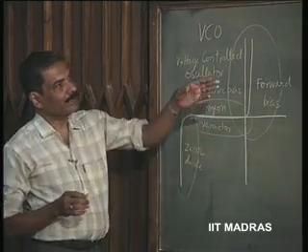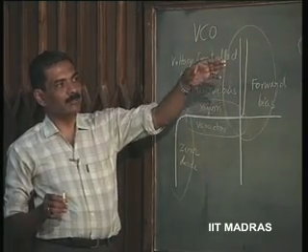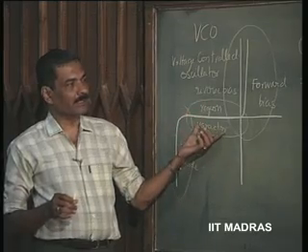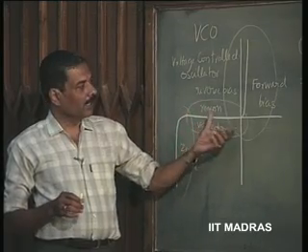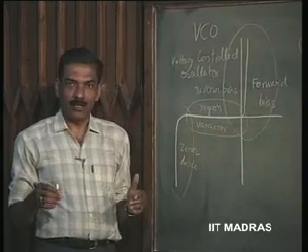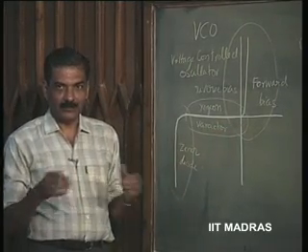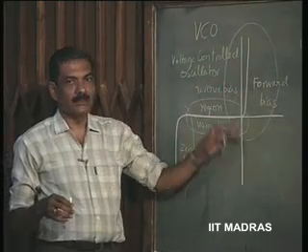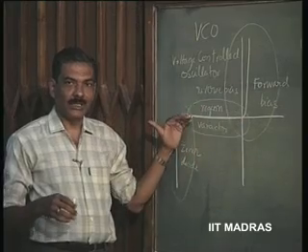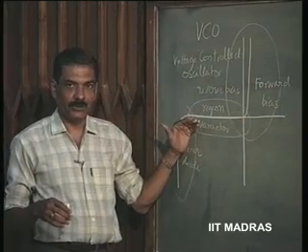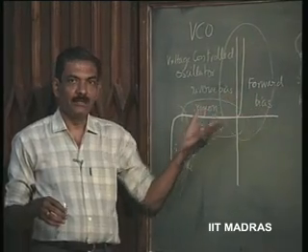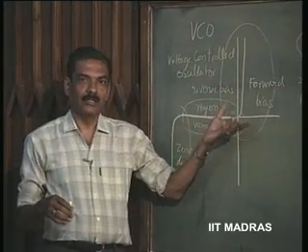Here he will maximize the ratio between C max to C min, and specify what value of maximum capacitance it has, and then here he will say at what forward current it has to be operated, what is the average forward current, repetitive forward current, all these things when it is being used as a rectifier diode. What should be the peak inverse voltage rating of this if it is to be used as a rectifier diode? These are the different ratings. So, different diodes have different emphasis on the ratings.